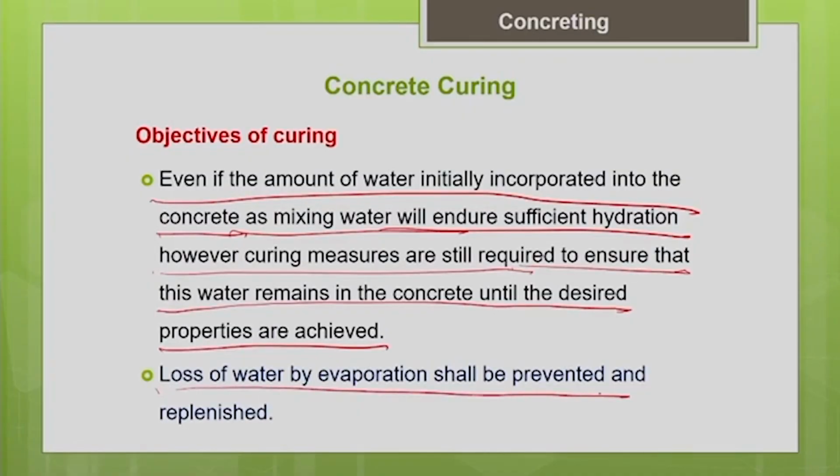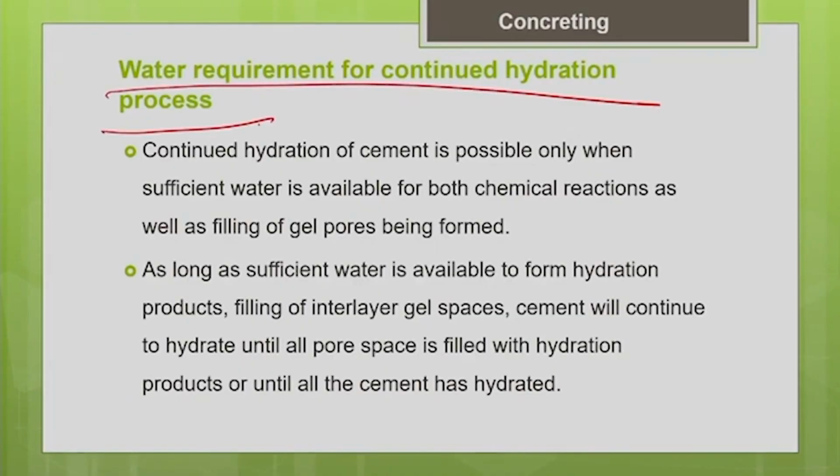Loss of water by evaporation shall be prevented by curing, and you can also supplement the water which is lost. That is the main purpose of curing. The main purpose of curing is supplying water to the concrete, so that the hydration process keeps continuing, and you get your desired microstructure, strength and durability of your concrete. Now, the water requirement for the continued hydration process, as I just mentioned. For the hydration process to continue, we need water.